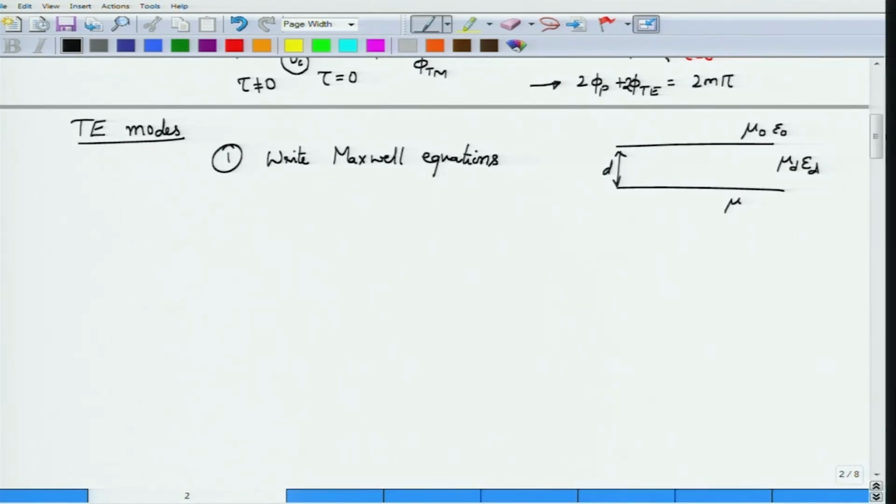The answer is that it cannot really be done so, but we are going to use this idea of having air just to simplify the mathematical analysis. A more realistic case would have been a different epsilon over here, so maybe a different substrate material, which would be more realistic, but the analysis of that is slightly difficult. So, we are not going to do that one. For us, the cover as well as the substrate both are air, having parameters mu 0 and epsilon 0 completely describing them. Okay.